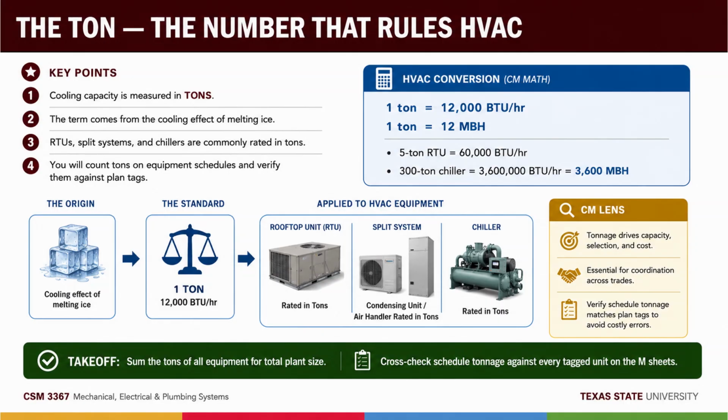And here's where cooling gets its own personality. For cooling, the simple delta T lies to you on sunny surfaces. Think about a dark roof in July. Air temperature, 98. Touch that roof. You can't. It's 150 plus. The sun has driven the surface way past air temperature. So the real temperature difference pushing heat into the building isn't inside to air, it's inside to a solar-baked surface.